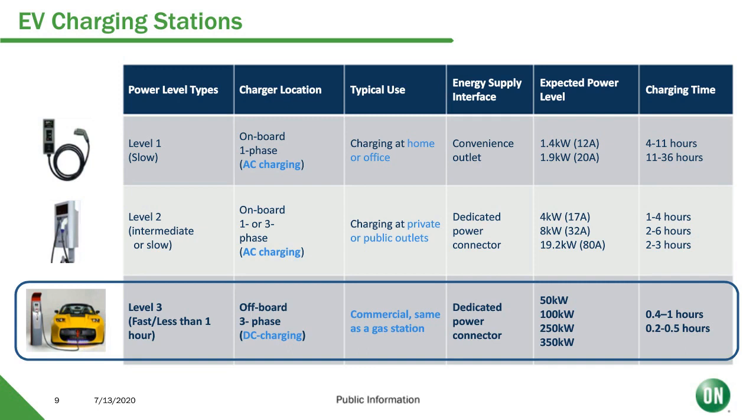Our key interest is in the level 3 or DC charging and DC fast charging, where power conversion is happening in the pole itself. Here, power density is going to be critical, and is where we see a lot of adoption of silicon carbide, as you're trying to fit up to 350 kilowatts into a pole, and space is, of course, a priority, as you don't want these gigantic stations consuming a lot of space and intimidating users.